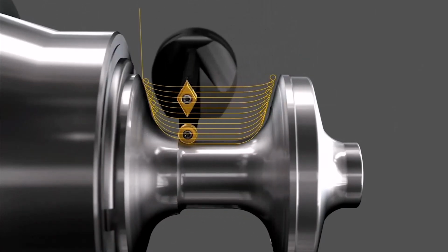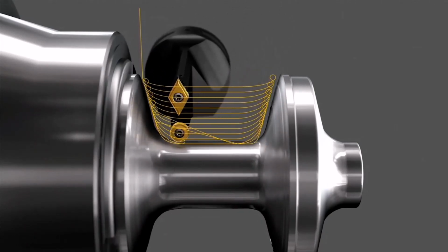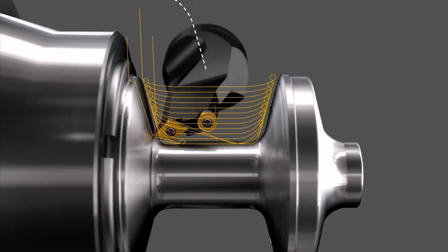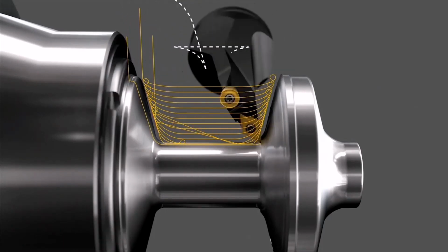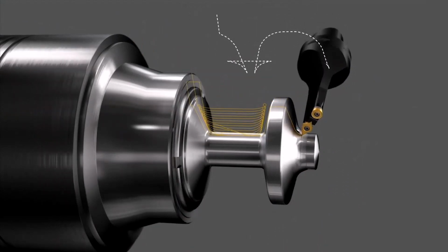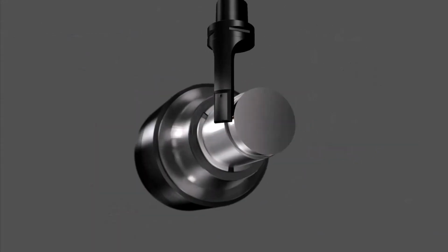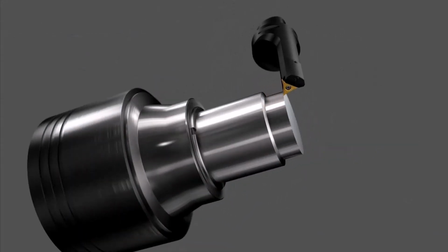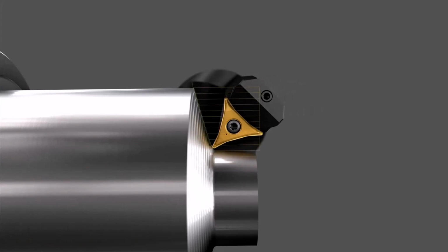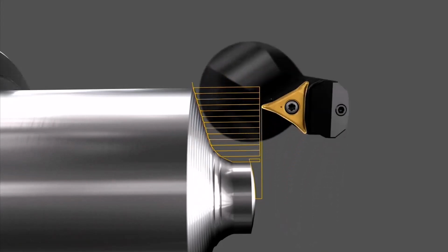Well, there are several reasons why we sweep the insert. We can have a burr-free cut. We can have no blend lines around left and right-hand features. We can control the chip thickness for maximized chip control. And we can engage all of the nose radius of the piece of carbide, which sometimes we don't always do. This allows us to get the maximum value out of our piece of carbide. It allows us to have a maximum quality part, no blend lines, no burrs, a seamless cut. It's more rigid. All these things add up to increased throughput. Absolutely. More rigid, you can push the tool faster.